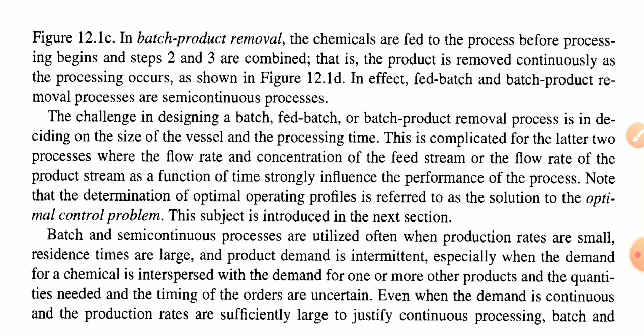The challenge in designing batch and fed-batch processes, and batch product removal processes, is in deciding on the size of the vessel and the processing time. This is complicated for the latter two processes, where the flow rate and concentration of the feed stream, or the flow rate of the product stream, as a function of time strongly influence the performance of the processes. Note that the determination of optimal operating profiles is referred to as the solution of optimal control problems. This subject is introduced in the next section.